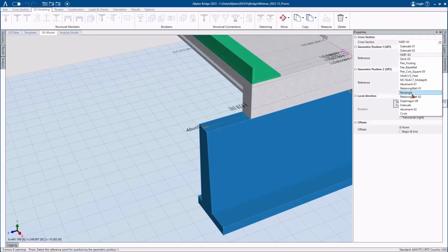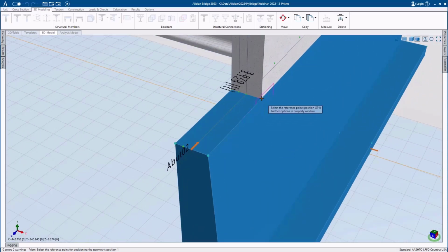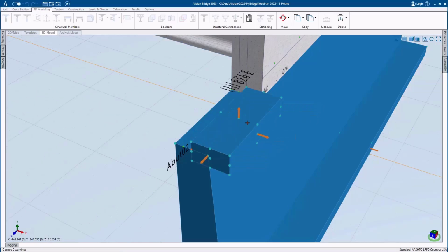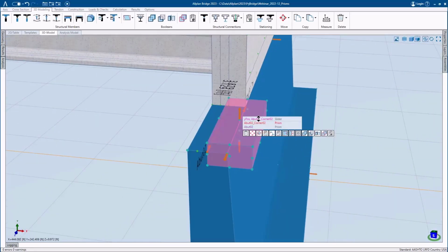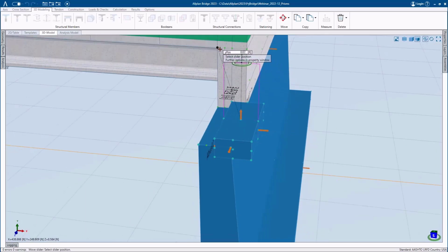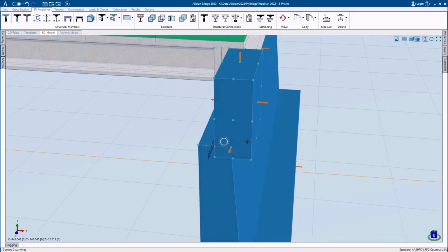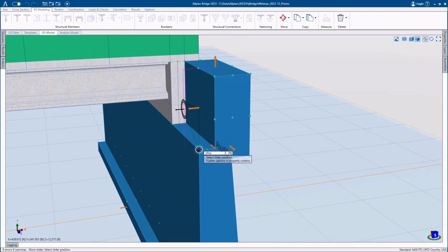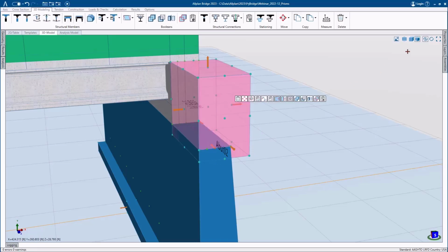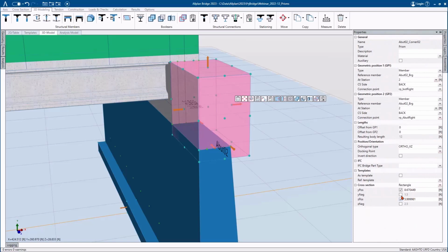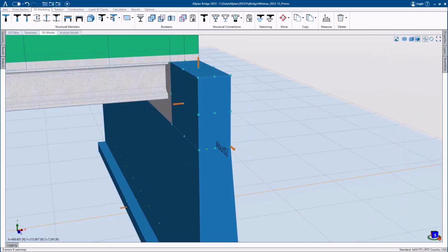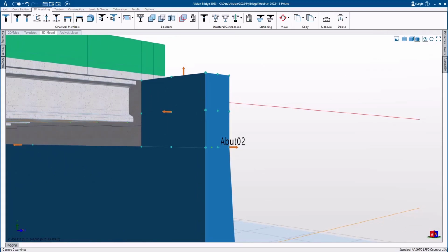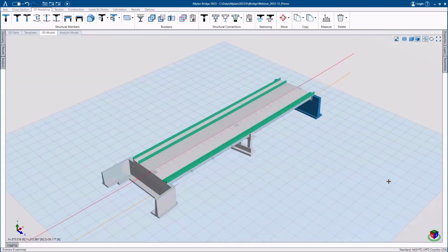Again, I want that simple rectangular cross section. We'll just extrude it from one end to another. Then, of course, easily manipulate it into position by selecting the sliders and changing the values by clicking on other structural members already in the project. Then let's go ahead and, rather than manipulate the last two sliders, we'll set those values to 0. Recalculate the project. And we can already see our abutment is beginning to take shape.